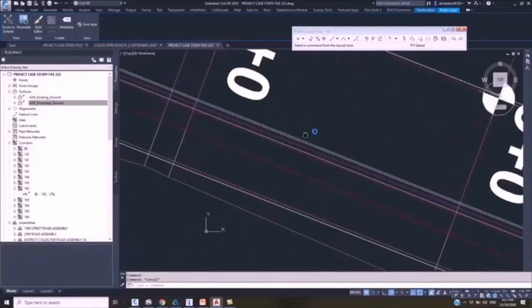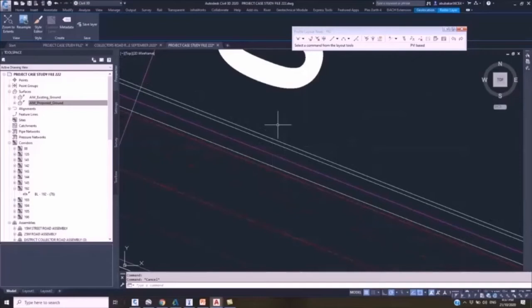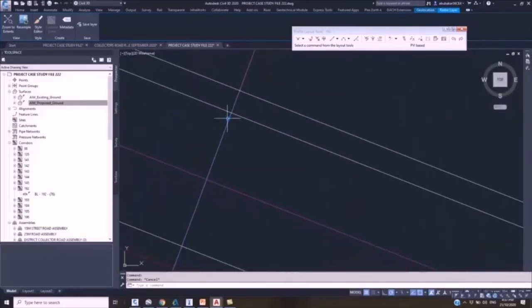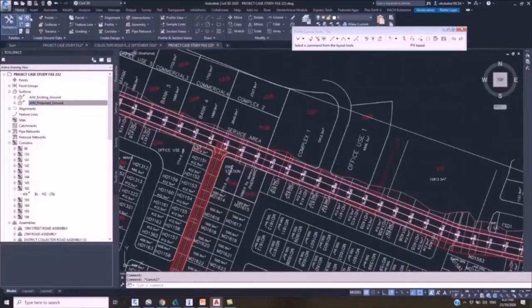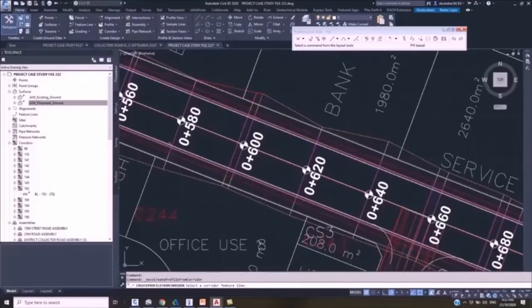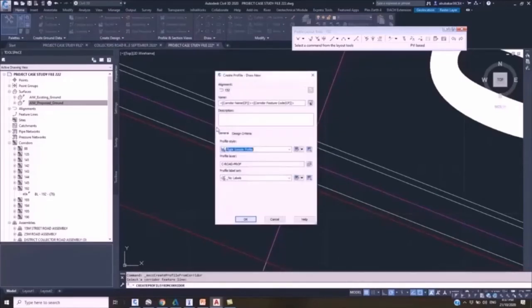Now, with the updated version, I can decide that the stormwater line for the invert level, with respect to the extension of the line, should be defined in the profile as well. So in that case, if it's an open channel, I can now create what we call profile, create corridor from profile to reflect the corridor flow line. So this is the flow line, this color code I selected. When I selected it, I can now stage drainage invert level for the workflow.